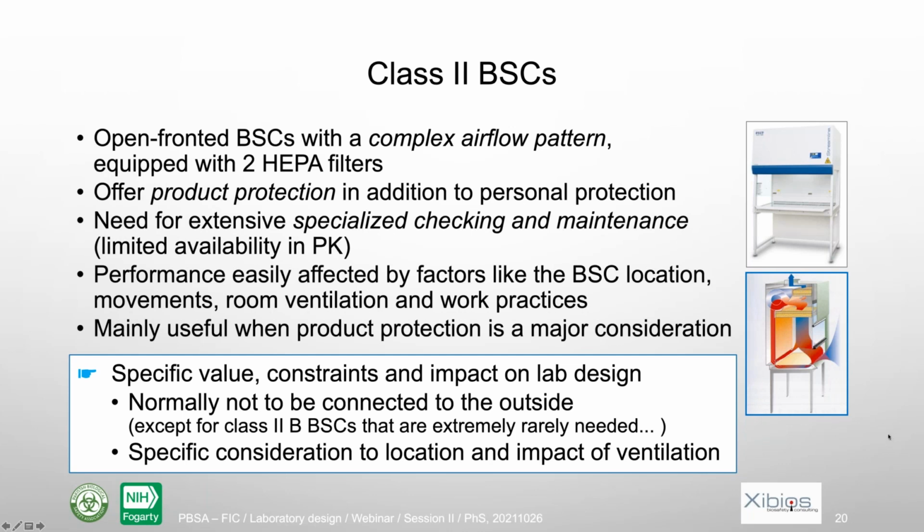Its main value, as I said, is that it also provides some product protection. But the personal protection is not as good as with a class 1 biosafety cabinet. Why? Because that airflow is quite sensitive, and so you might have some disturbance here. Because of that, the location is much more important, but also work practices and so on. Also, it's a more sophisticated equipment, and so you will also need more checking and maintenance, and all that will make it more expensive to use in the long term.